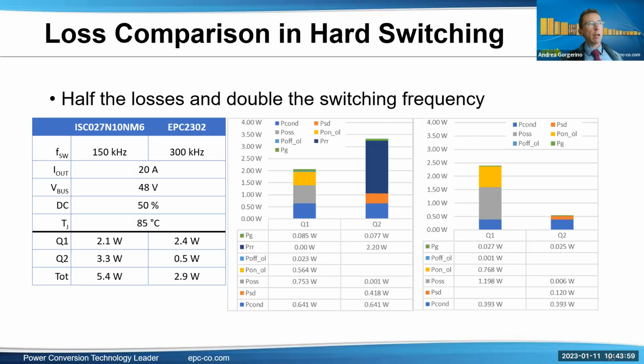But the power loss is instantaneous power loss. The average power loss also means how long you're spending in that condition here and there. So what I did in this calculation here is I've used different dead time for silicon and GaN. The way I calculated the dead time, I just used the same criteria for both. I took basically the sum of all of the transition time and I multiplied it by 2. I don't remember the exact number. It came out to something like probably around 12, 15 nanoseconds for the GaN, and maybe something like 60, 70 nanoseconds for the silicon FET.